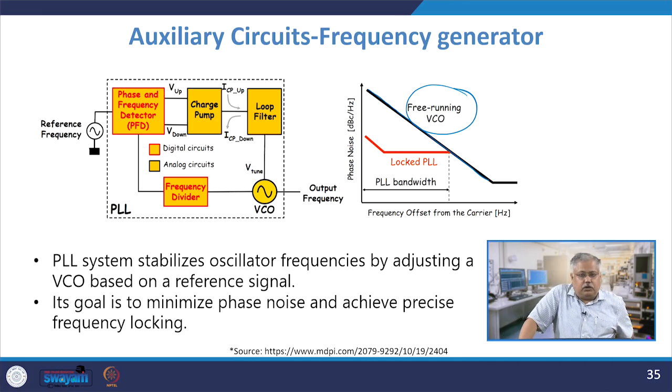However, please understand one important property: whenever we design a PLL, or for that matter any oscillator, you need to ensure that the phase noise or the thermal noise is as low as possible, because your signal is so small that if the signal floor and the noise floor become very close to each other, there will be a big problem segregating these two signals and filtering them out. So, one way is to keep your noise floor very small compared to your signal floor. It might even go as low as femtovolts, the average RMS value.